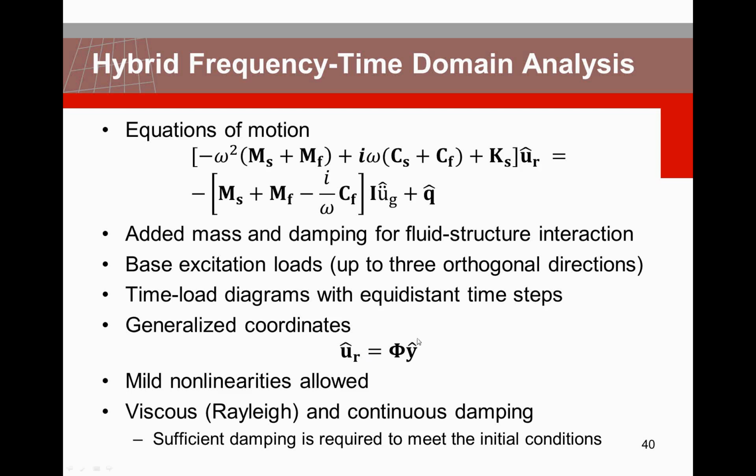So you can imagine if you have so much damage that the mode shape is not matching anymore, then this whole equation of motion is not valid anymore, and your solution is also worthless. But in case you have, say, local cracks or local interface behavior, with this hybrid frequency time domain analysis you can resolve it. You can take, for instance, compressibility and first order surface waves of the fluid into account.